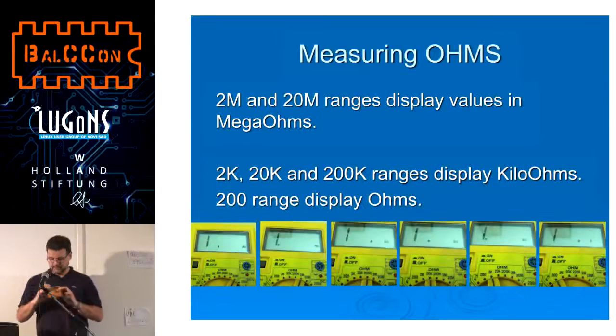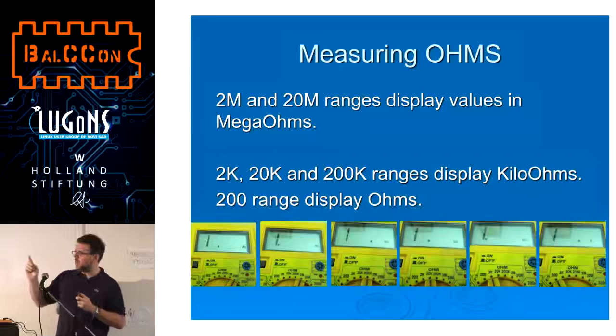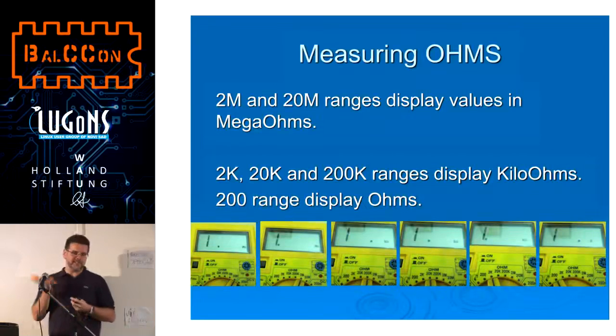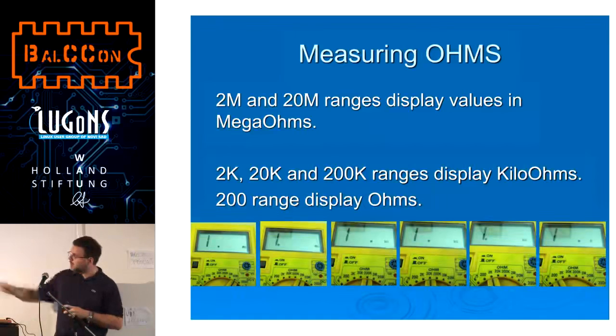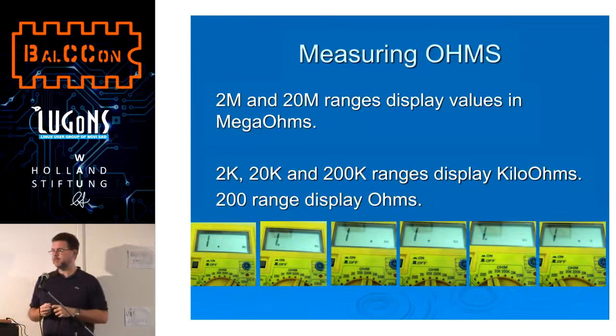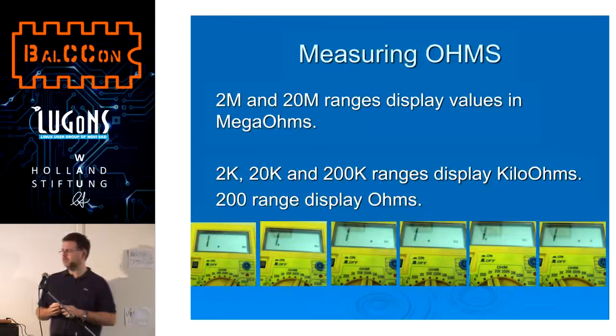Why is number 1 on this multimeter and it's measuring nothing? Well, it does measure. It measures resistance between these 2 probes. Resistance between 2 probes now is infinite. And infinite is very large. And I told you that 1 means over range, so it can't measure infinite. You can see that the decimal point is changing its place depending on what range you are going to measure.